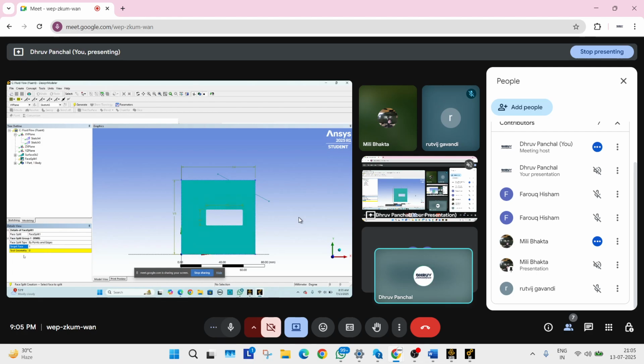Okay, that is selected. Now for the tool geometry we need to select the new sketch by edge selection, using the edge selection filter. First click on the yellow color, then select. Perfect. Click on apply.